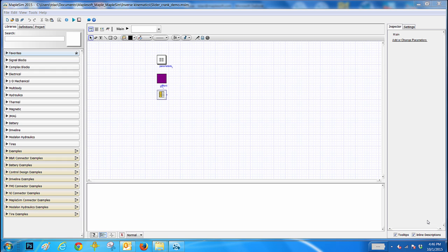So we are going to learn how to use Maple symbolic techniques to obtain the kinematics and kinetic relations based on the mechanical systems in MapleSim, and then use the CodeGeneration capability in Maple to generate C subroutines that can then be embedded with any programs that support the C language. Inverse kinematics and inverse dynamics refers to the use of kinematics and kinetic relations to determine the joint parameters or forces that provide a desired position of the end effector.